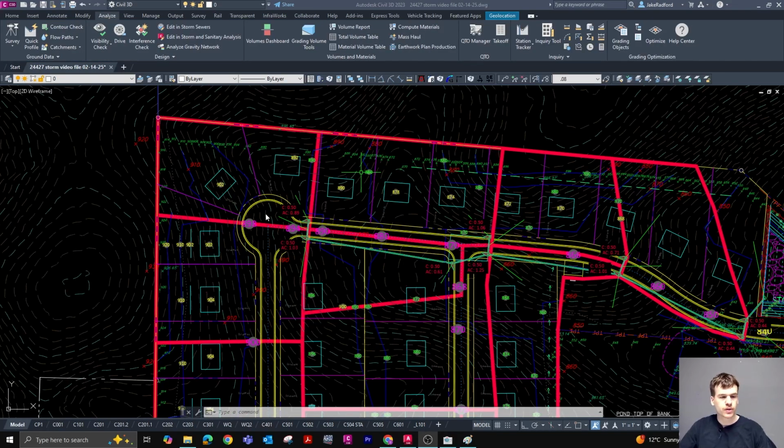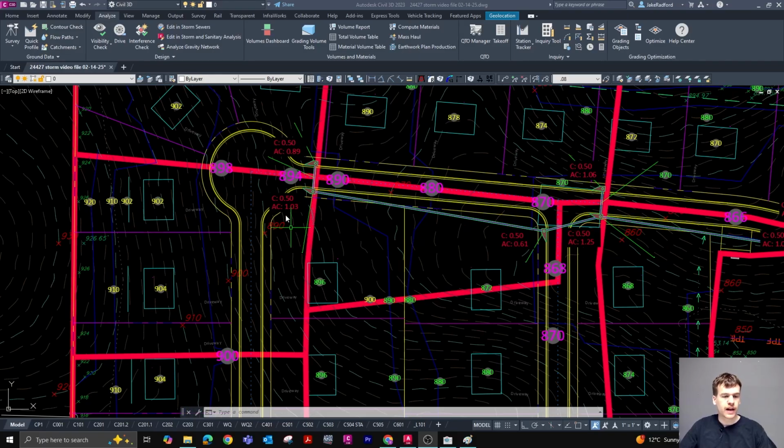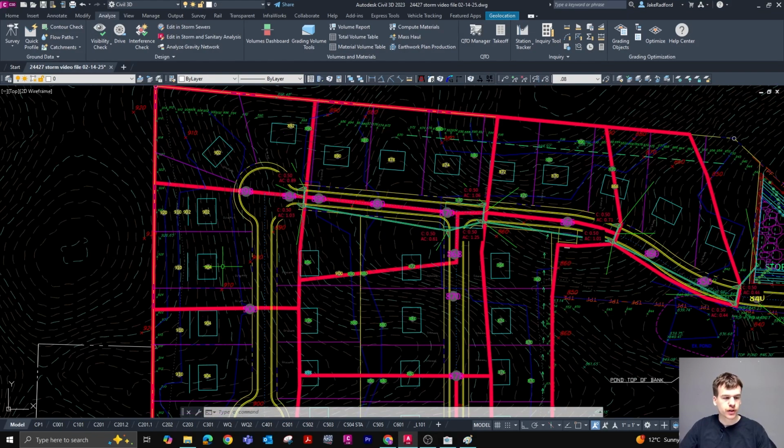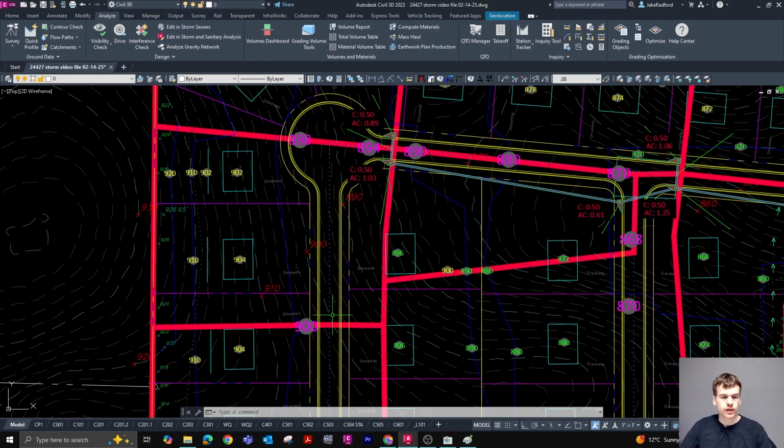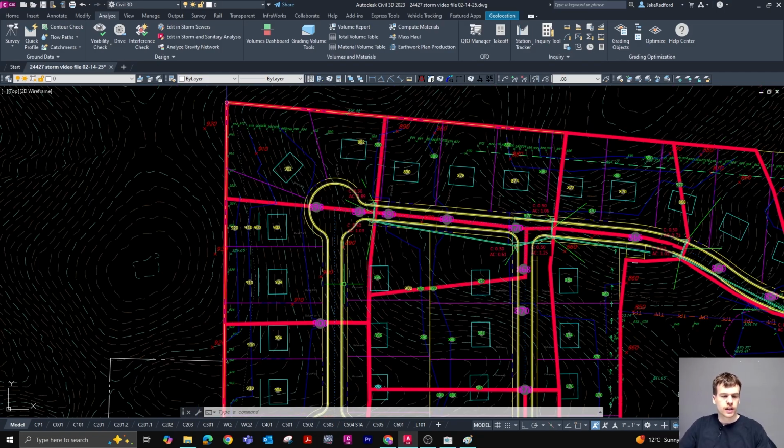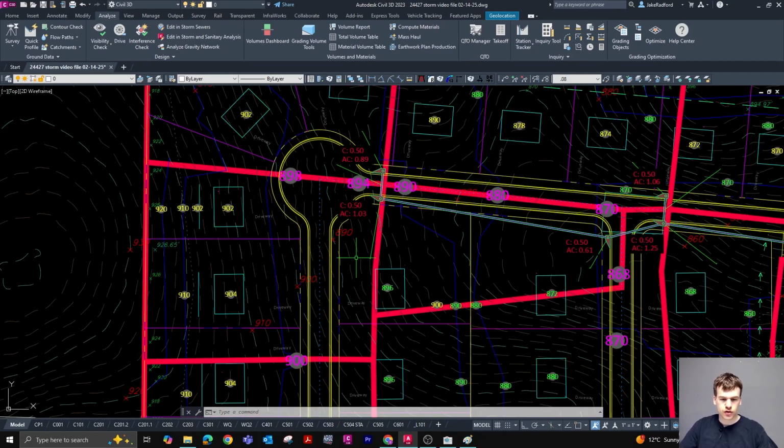In order to establish the runoff coefficients that we're going to punch in for each individual inlet, we'll have to have our drainage areas already delineated. So once again, as stated before, you're going to look at your proposed grade, and all of the infrastructure that's being put in, like the road, where the gutter is, etc. The more you do this, the more accurately you'll be able to do it. But accuracy isn't super important here. You don't have to know exactly where every single drop of water that lands on the site is going to run off to. You just have to get a general idea of what the acreage is draining into each inlet.